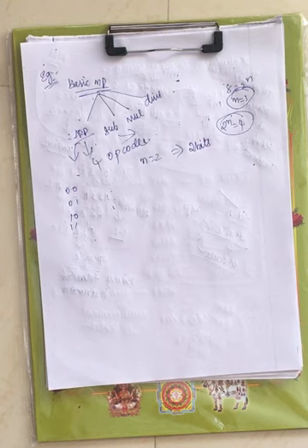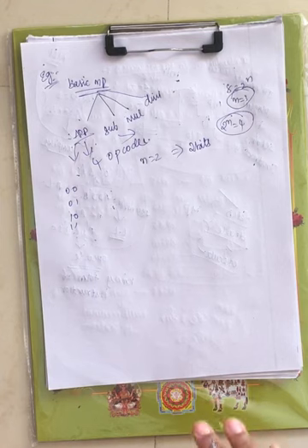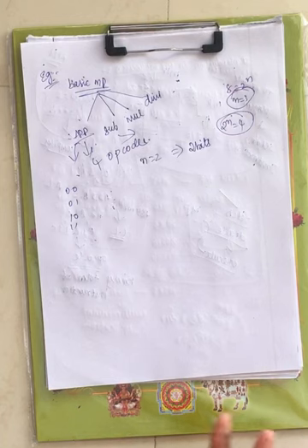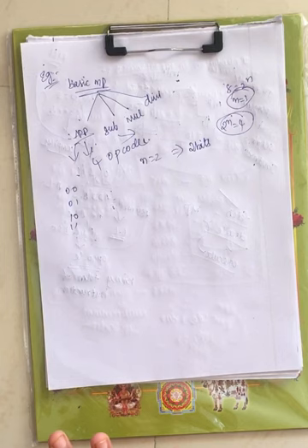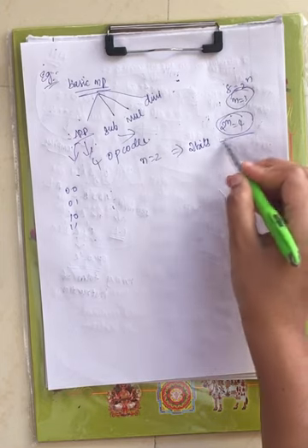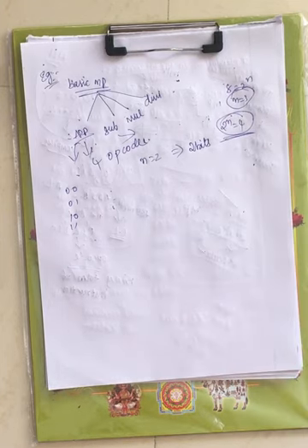That can be extended for a 4 instruction processor, a 32 instruction processor, and so on. Here we are assuming a basic processor which has only 4 instructions: addition, multiplication, subtraction and division. Since it has 4 instructions, we will have 4 opcodes. Opcode is nothing but the binary form of an instruction, after converting the instruction into low level language. Based on this scenario, the opcode will be of 2 bits.